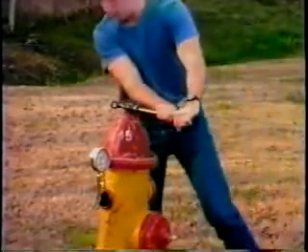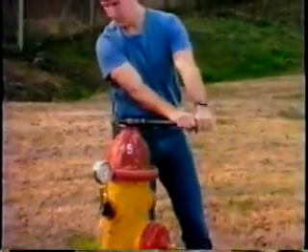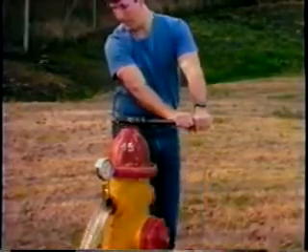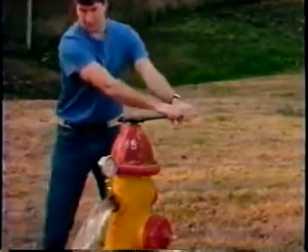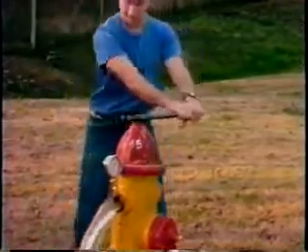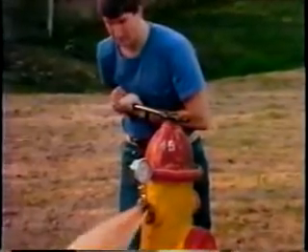The person at the residual hydrant needs to control the test because in some cases you may have several individuals opening hydrants, and you don't want them to be opening them simultaneously. Instead, you'd want the hydrants to come online one at a time. And the individual at the residual hydrant is in the best position to decide when it's time to open up another hydrant.